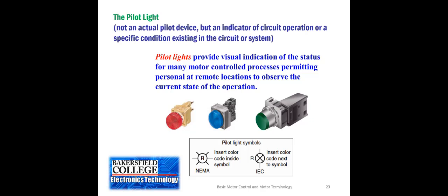Now remember, there's also a device that's called an annunciator. Its purpose is having multiple pilot lights behind a front panel, where each light has a label on it, so that when that area glows, you read exactly what condition is happening. Some of those pilot lights on an annunciator come on for good things, like the circuit is operating properly, you have proper pressures, proper temperatures.